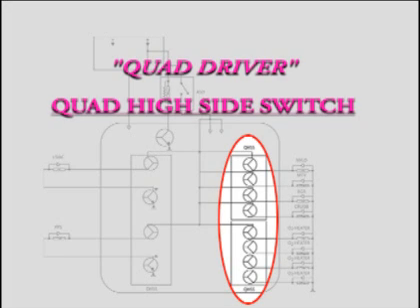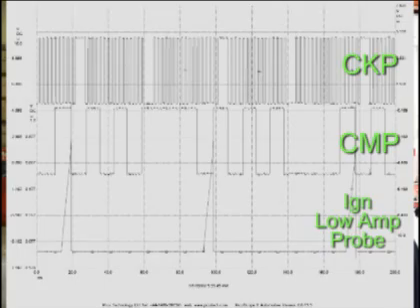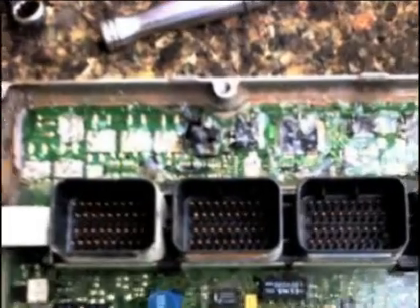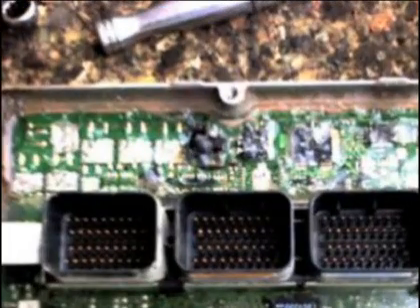The PCM does not include a quad driver error code for this system, and a failed quad driver can cause the same code here as in the example. The waveform shows the missing low amp waveform and PCM with a burned quad driver.